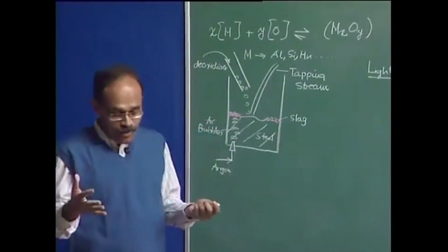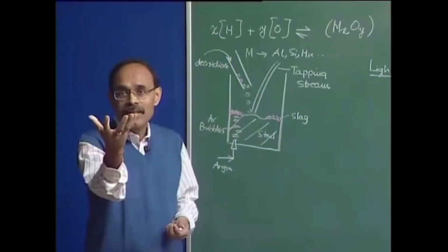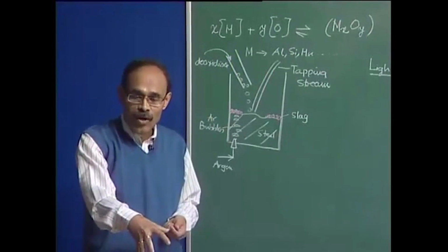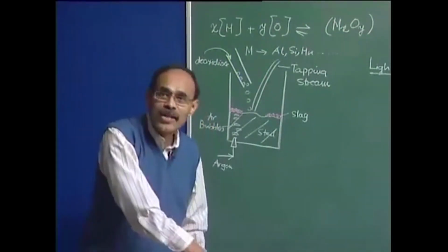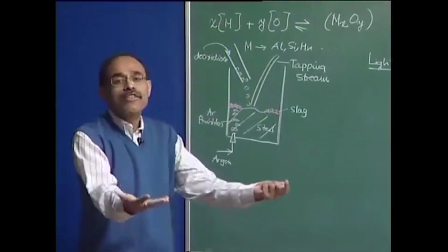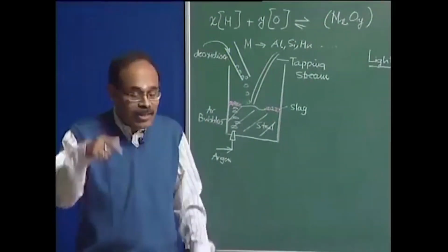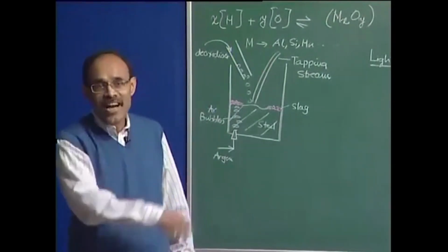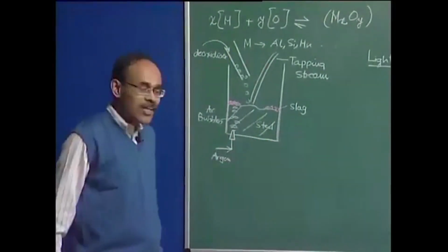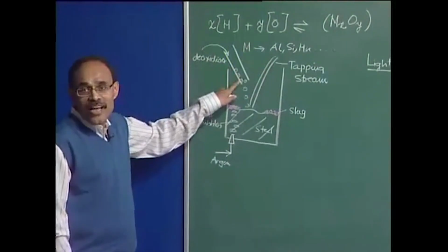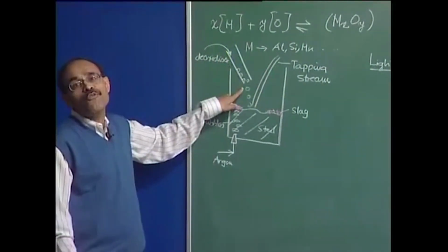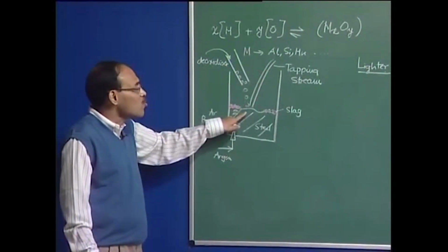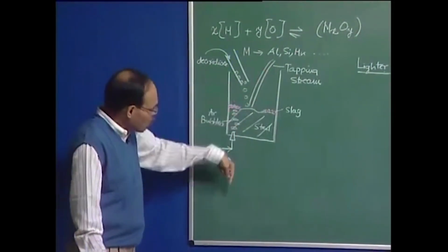For example, go to a swimming pool, take a ball, and try to submerge the ball underwater. Suppose you force the ball with extreme speed onto the surface of water in the swimming pool. What did you see? The ball does not really penetrate much, because the density of the ball is substantially smaller than the density of the bulk water itself. So even though the deoxidizer element is falling from a height of 3 to 4 meters in a typical steel melt shop, these deoxidizer elements are going to hardly go subsurface.